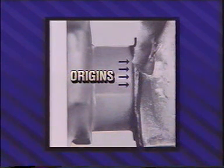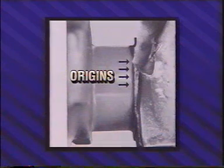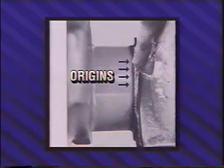The beach marks shown here were produced by a combination of variations in loading and the periods of rest normally experienced by an automotive crankshaft. In this case, the crankshaft is a ductile iron. Fracture originated at a notch in the root of a repair weld. The final fracture area was very small, indicating that low load levels prevailed.